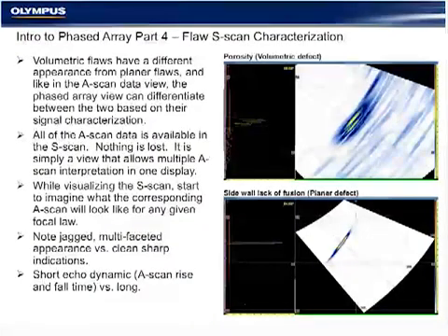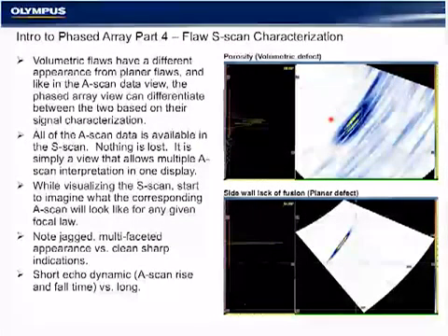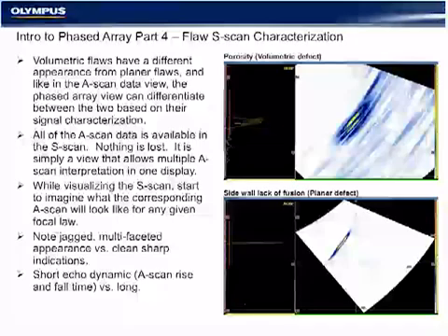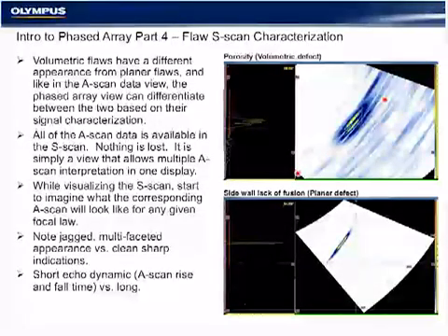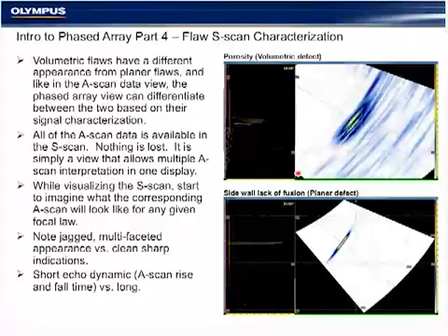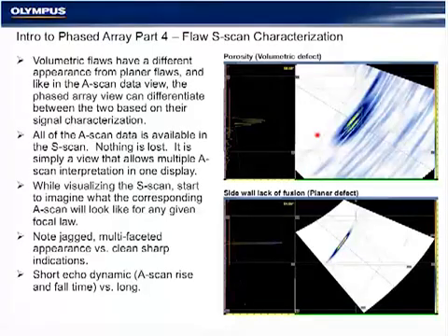When we see the same indications in the S-scan data, we can see the indication from a multiple group of beams spread out between 45 and 70 degrees. So the expert was able to characterize this on an A-scan correctly, and obviously when it's inside the weld overlay and we can see the data from all of the angles in the S-scan, we can more easily and with more confidence identify this as slag.